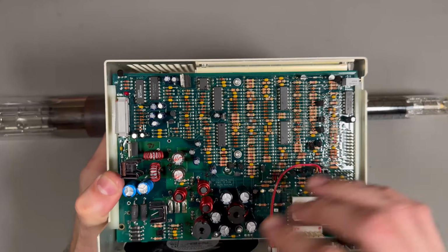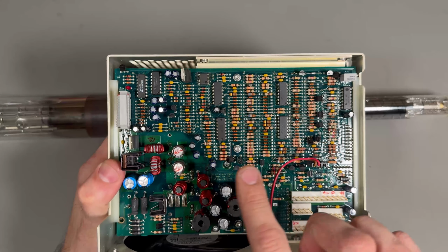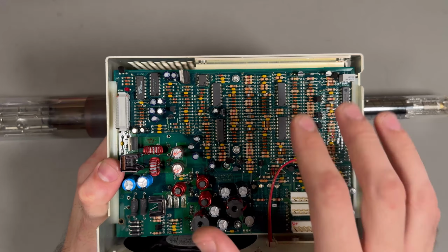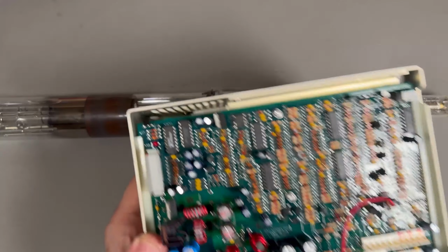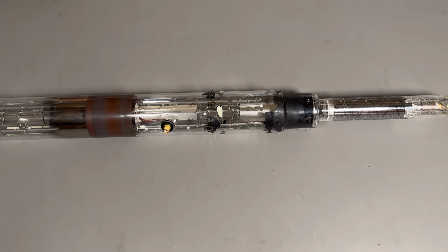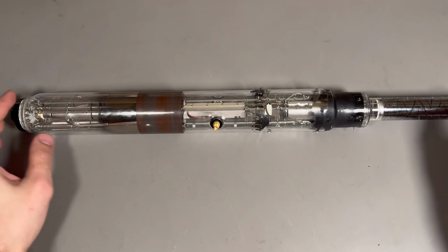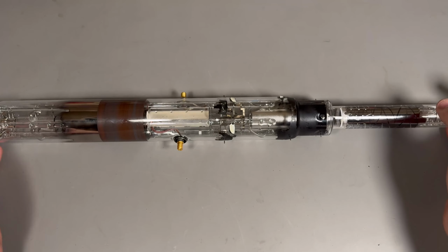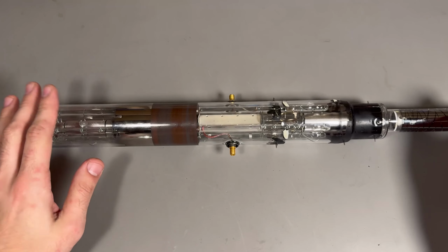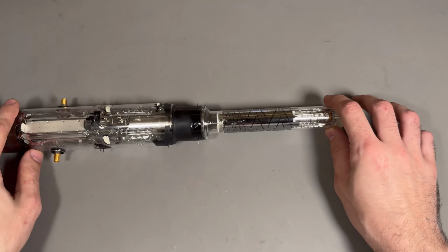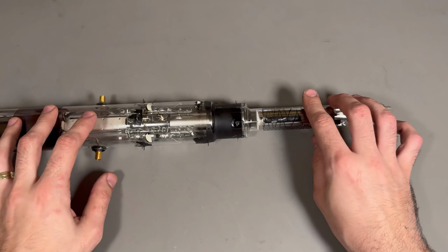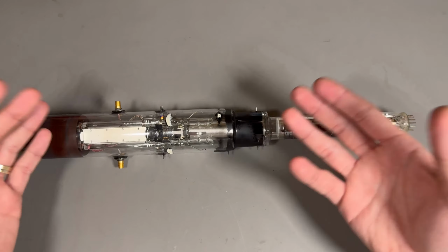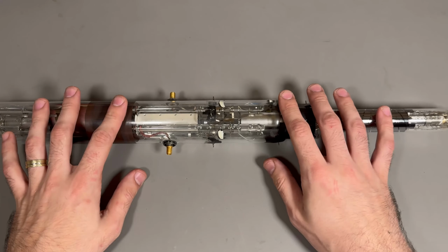So every rail is protected against over voltage and over current. And in case you're not seeing any shunts, the shunts are traces of the PCB on the inner layers. It's crazy, and it's very, very nicely designed. So, as I was saying, this thing had a bum tube. So this tube is unfortunately dead. Either the cathode is completely dead on the CRT side or in the Vidicon side, or the target is blasted, because at 100% beam current, the device couldn't acquire any reading whatsoever. I verified the high voltage power supply and it works, so it's not this.